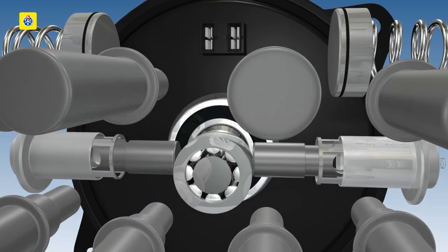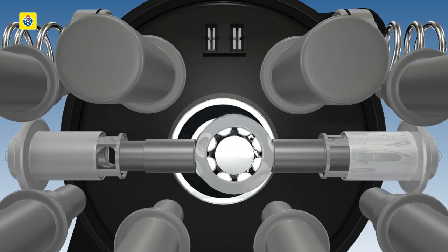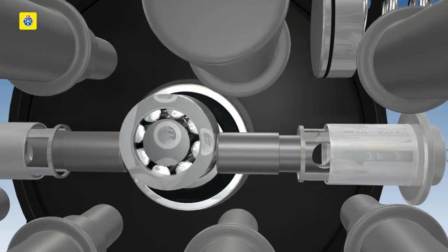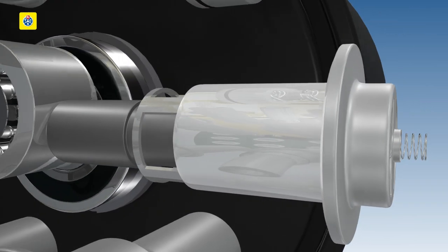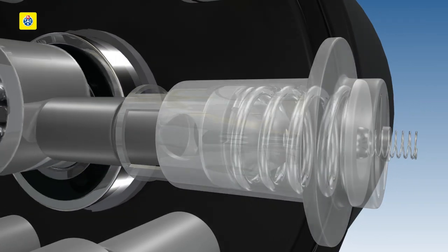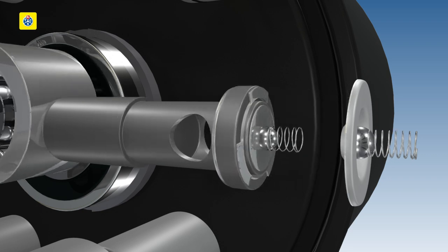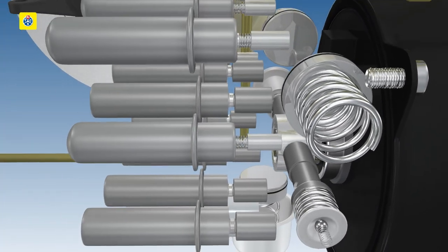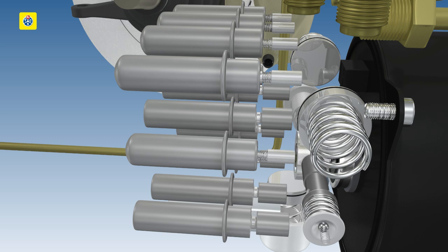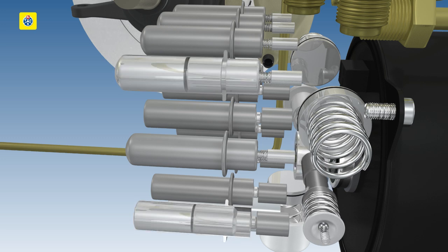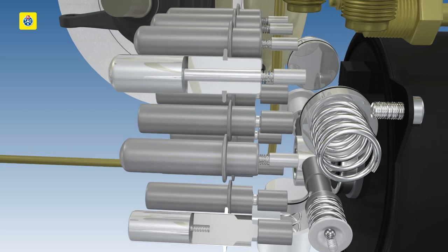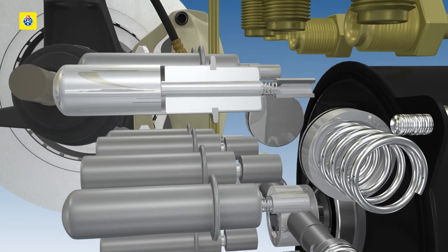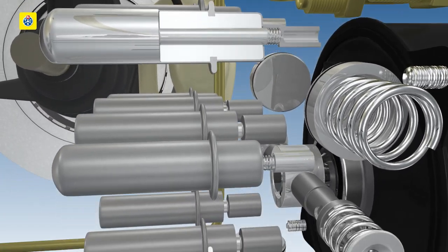An electric pump is switched on for this purpose. This drives pump elements that generate the pressure in the hydraulic circuit. Inlet and exhaust solenoid valves control the maintenance, release, and buildup of braking pressure on locked wheels.